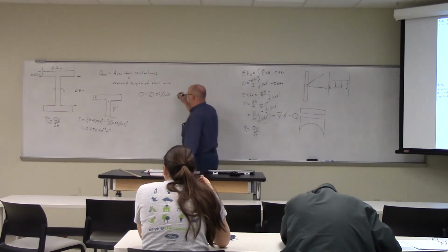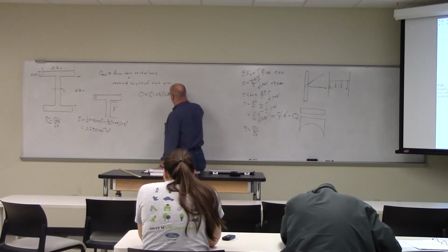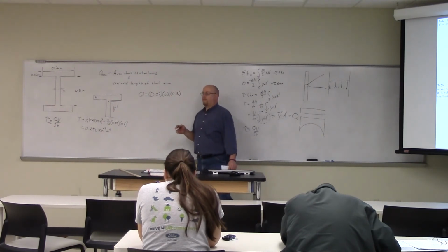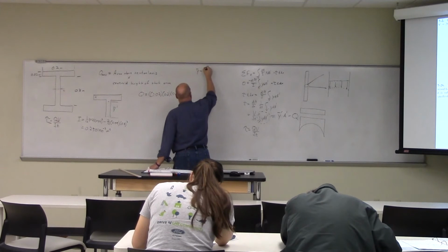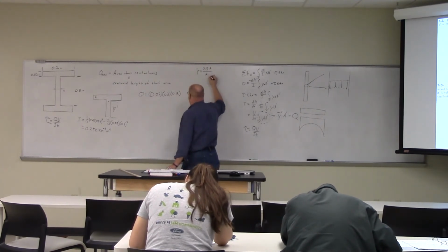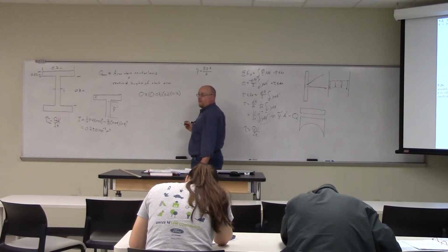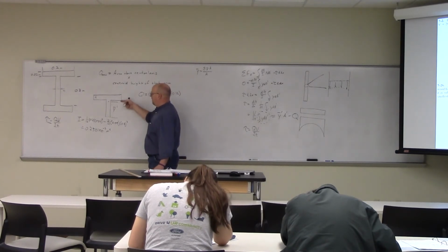So this is the area, what's its centroid's position? Not quite. Let's see what's in this section. Do we just add the centroids? Yeah, because the way we found the centroid was the sum of y times A for each individual piece, divided by the total area. This area is over here, so we just have to sum the other pieces. Remember that? Okay, so 0.16, because this one is 0.15 plus 0.01